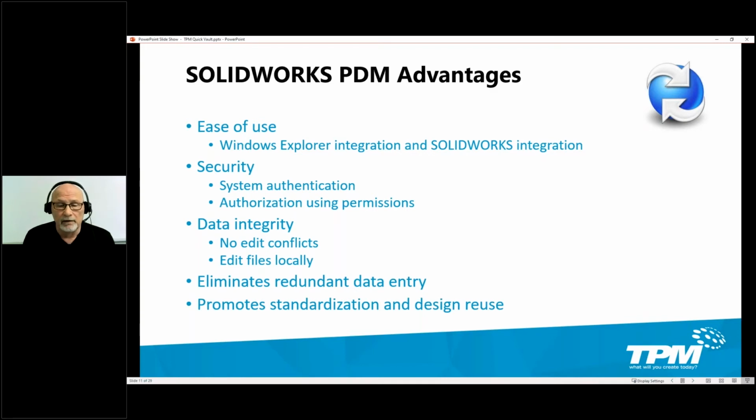And it promotes standardization and design reuse. If you use SOLIDWORKS Toolbox, you can put that in the PDM Vault and manage it in there. If you have standard templates that you want everyone to use in the company, you can put them in the PDM system and have the SOLIDWORKS file location options point to the files in the PDM system instead of everyone having their own set of templates that they're working from.